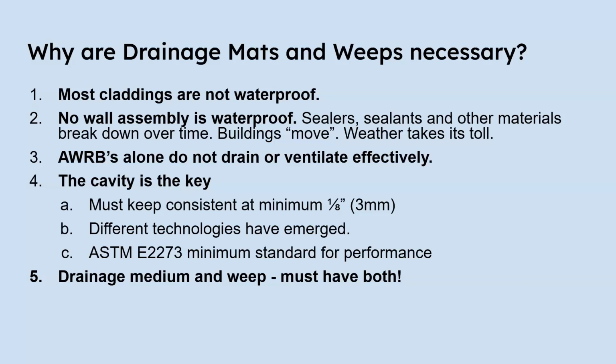You have to keep that minimum of 1/8 inch or 3 millimeters. That's per John Straub and many building scientists who agree that because of the capillary action of water, if the gap is less than 1/8 of an inch, the water itself can hang up on one side or the other and not drain effectively. So the consistent gap at a minimum of 1/8 is necessary.